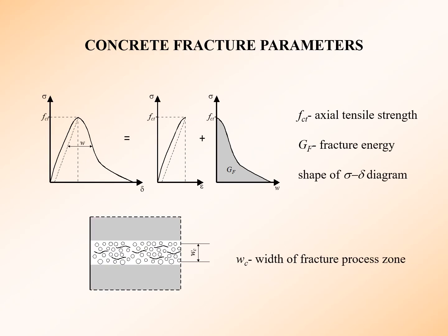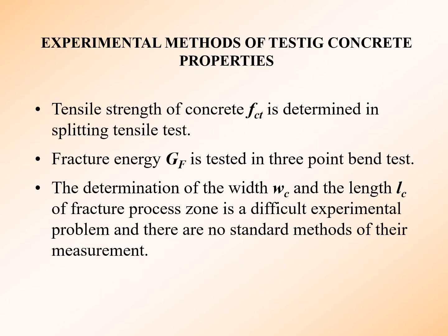Some additional concrete fracture parameters should be determined, such as fracture energy and width of fracture process zone. The methods of testing tensile strength and fracture energy are well known, but there are no standard methods how to determine the width of fracture process zone.